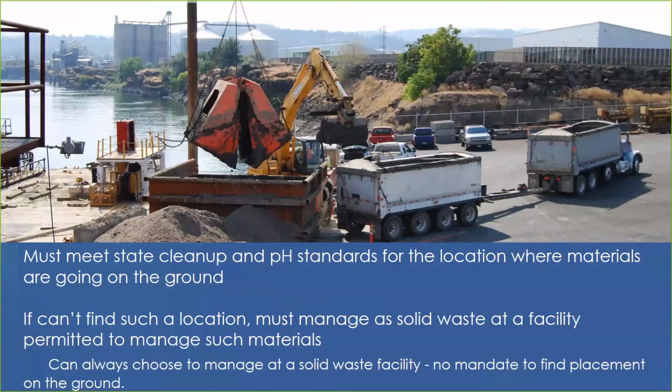We also have set a pH standard for releases that affect the pH of material, and we have that at 4.5 to 9.5, or in line with natural pH conditions where you're planning to put such materials. So using the materials in ways that are allowed in the rule is considered clean soil or clean dredge material handling, which is not solid waste handling and is excluded from the rule applicability section. This is real similar to if you land apply manure at an agronomic rate, it's also excluded from the rule. So it's a material as well as the use that are excluded.